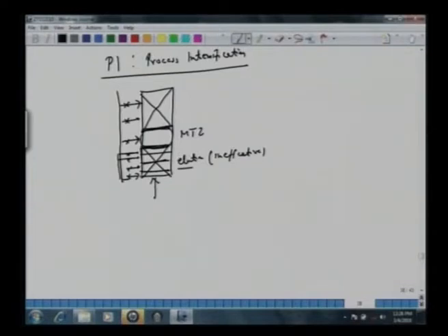So it's a wastage of this spent adsorbent. One has to regenerate this. So activity takes place only here, neither here nor here. So this is one way of process intensification which is quite interesting to note. There is a wave which moves, which represents the front. So there is a propagation of this front in this direction, and one has to make the feed move like this to ensure that at any time the feed comes in contact with this, so the process is intensified. Essentially, one can show that we require a very small amount of adsorbent in comparison to the conventional process.